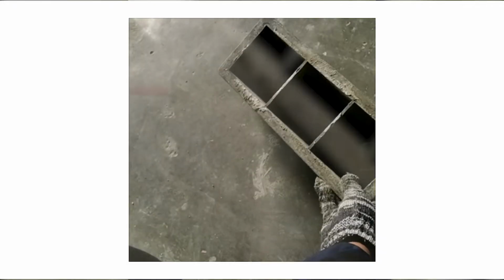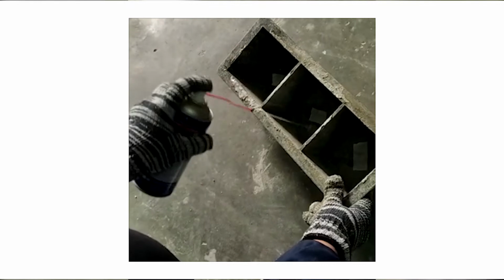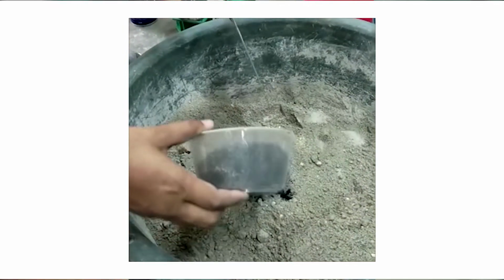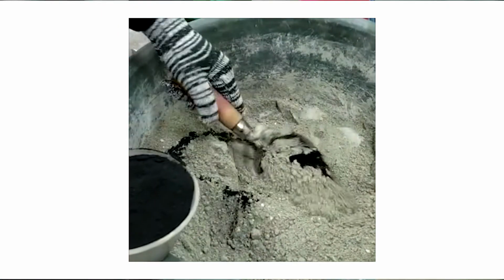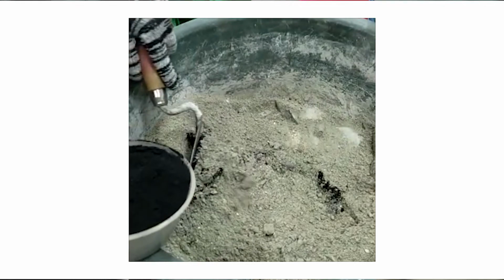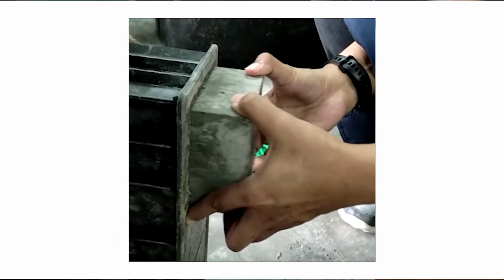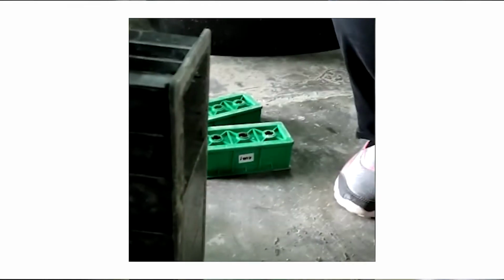The amount of RHA, OPC, fine aggregates and water required for the cube mold with a dimension of 50 by 50 by 50 millimeters was calculated. The mortar was mixed with RHA at different compositions between 5 and 20% to be used for comparison. Water to binder ratio was set at 0.44. All the mortar mixtures were demolded after 24 hours and then water cured for 28 days.